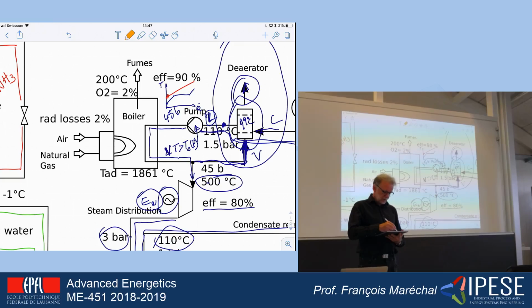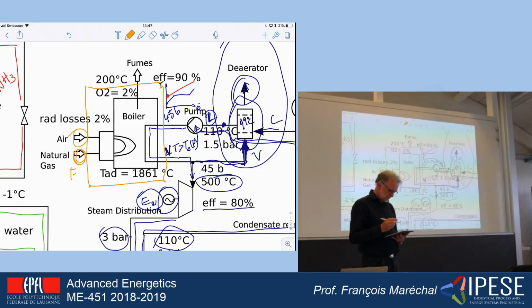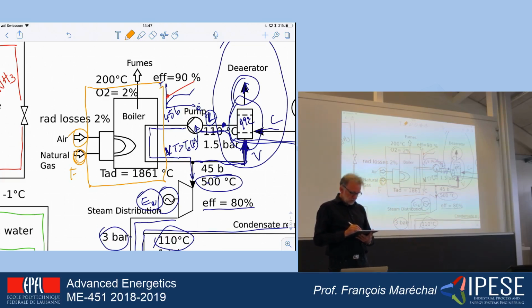boiler. So the boiler is going to be defined by this subsystem here, where you have the fuel that is entered. So this is the fuel. This is the air that is used in order to burn the fuel. This is going to be merged and do what we have modeled here by a flame, which is the combustion. And the combustion is going to create hot gases that will then be cooled down in order to heat the steam that is here, so that it goes from the liquid to the vapor state here.